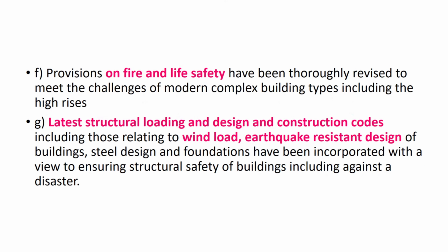This is a crime. Now you can understand what he has done, because you have made your civil structures and gone. Now the electrical person or the contractor comes and does his work. You can see here that more than 50% of the section of the column is gone, and that too at two locations. So you can understand the importance of all these activities. Many times we tend to ignore these things.